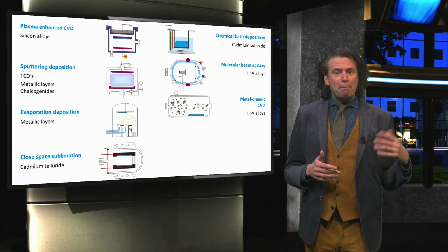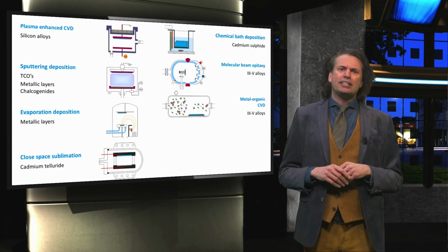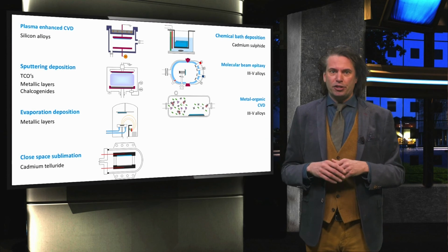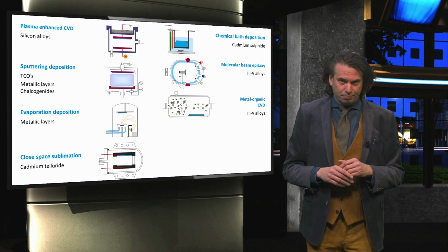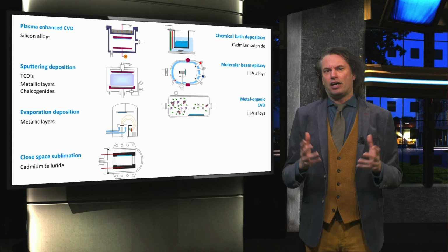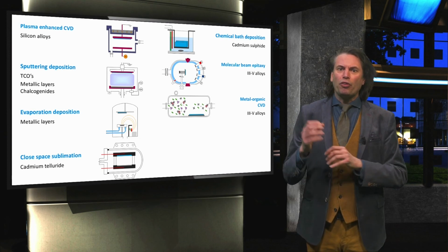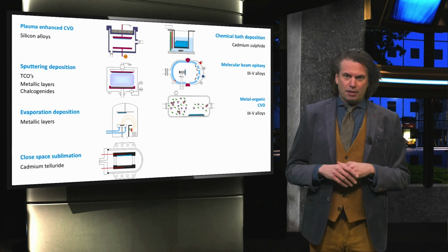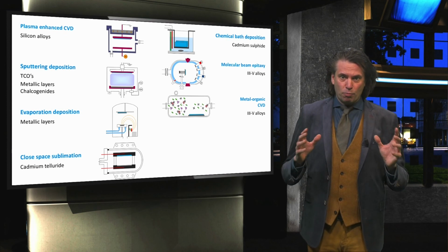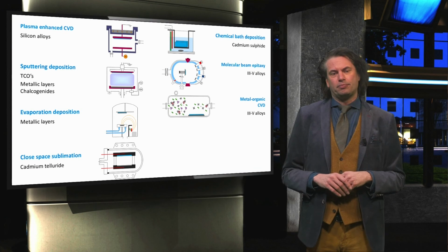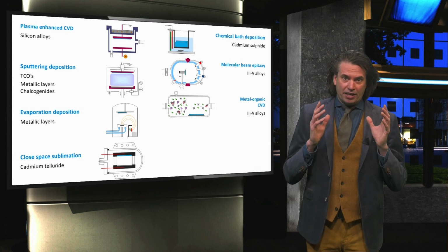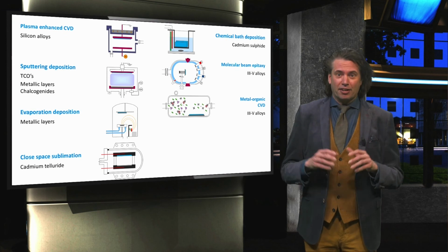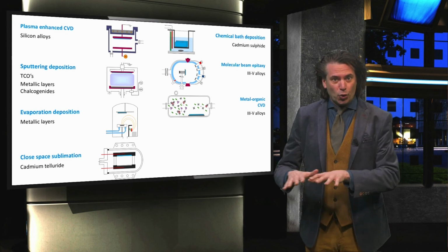In reference to MBE, MOCVD is cheaper, has a higher deposition rate and results in lower purity of the deposited alloy. For MOCVD, target atoms are bound to 3 hydrogen atoms or methyl groups and passed in gaseous form over a heated substrate. The elevated substrate temperature dissociates the precursor gas and a thin film of the target material grows on the substrate.